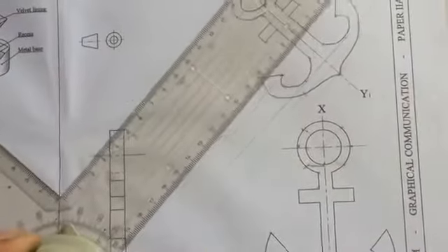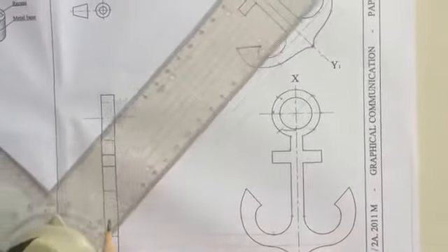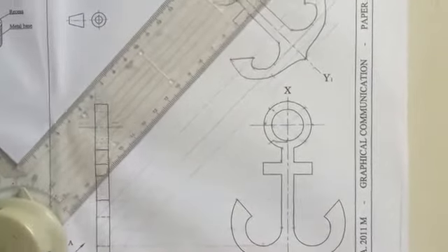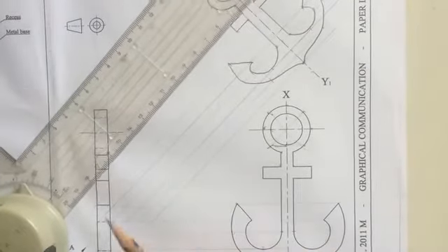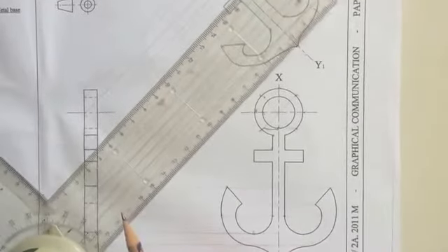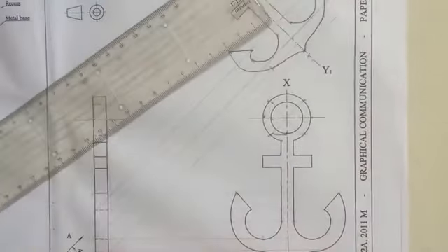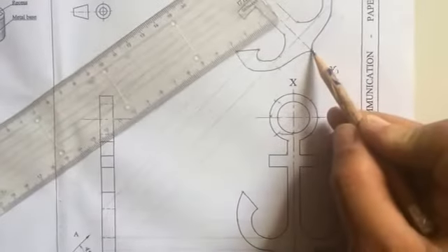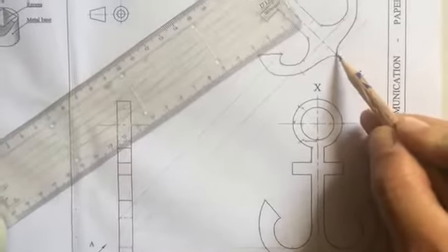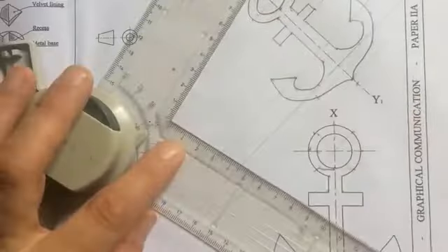Otherwise, you could do this, and I prefer this method, much easier. I'm just going to take one point, the bottom point. I'm taking this point with 45 degrees and project it onto the auxiliary view. So the front point is here, and the back face gives you here, which means that this is going to show the thickness of that distance.